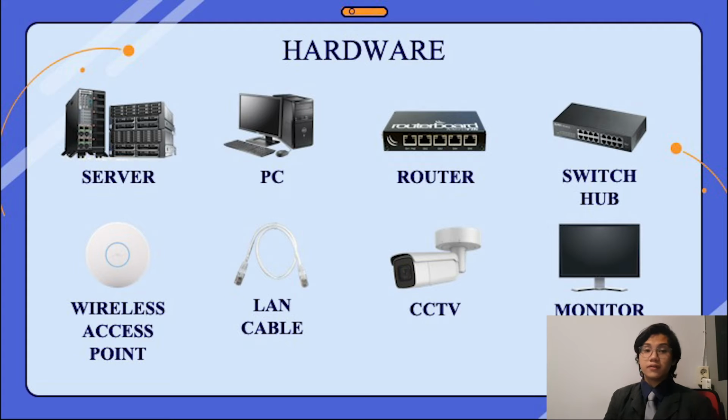And we use CCTV, the Samsung SCD-2080E. The function is to monitor all activities. If there's an accident, then CCTV can replay the accident and we can find out who did it. The specification that we use is imaging device 1/3 Super HAD CCD, total pixels 811 times 508, effective pixels 768 times 494.